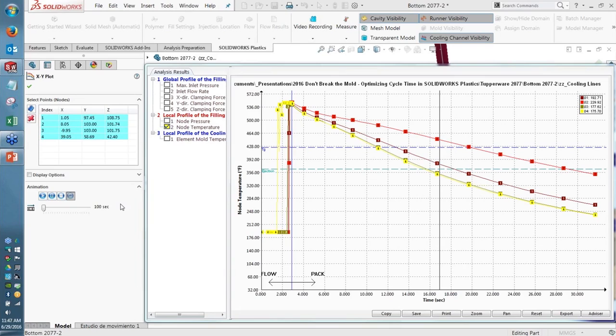So just slightly longer than what we had originally predicted with an ideal mold temperature. So thankfully we've validated that we will be able to design a mold that fills the parts quickly, that doesn't have too long of a pack time and doesn't prevent shrinkage to an unnecessary level, and that we've got a cooling time that's acceptable and also something that we can actually do in the real world with the right mold material and cooling layout and coolant.